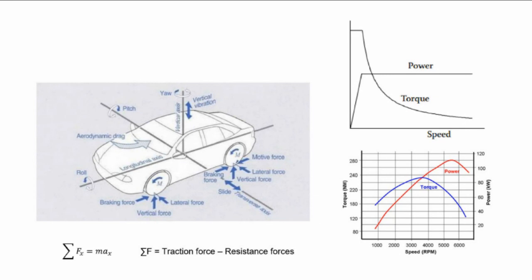In your first homework, you designed the DC motor. Very simple, but it is okay for us. You have torque input, speed input, and motor parameters, etc. You can design an electric vehicle DC motor model. You can select motor parameters, for example, 70 kilowatt. Also, maybe your torque will be 100 Newton meter, etc. Maybe you can add a gear.